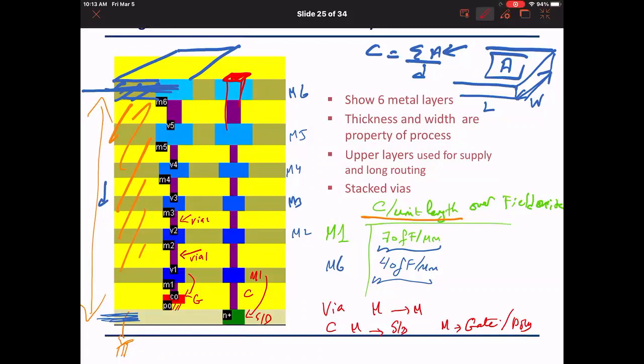Okay. Thank you. And you said something about the W getting larger as we go up? We will talk about it later, but the reason it becomes larger is this: if I have a big chip, let us say 1 millimeter or several centimeters, I have a wire going 1 centimeter, versus at the gate scale I have a wire going 10 micrometers. The lower ones I route at the lower wires, but the big signals that go long distances over the chip, like the highway on the map, have to be wide, have to be big, and have to supply the signal to many locations.